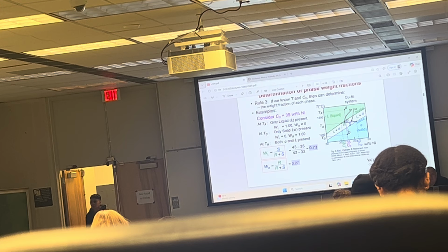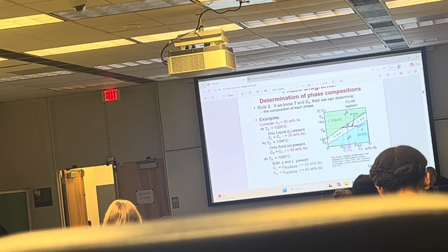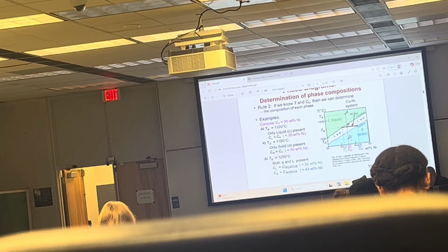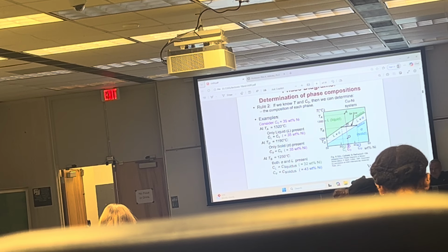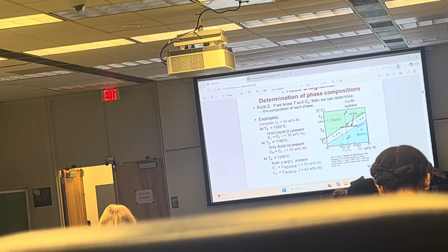So I just wrote the composition again. The composition C_L is for the liquid, C alpha is for the solid. What's C0? C0 is your alloy that you start with. That's what they gave you. That's your alloy. You made it, or you bought it. C0 is the initial concentration. You take this much nickel and this much copper and put it in a melting pot, melt it and stir it, however you made this alloy. Yes? Okay.